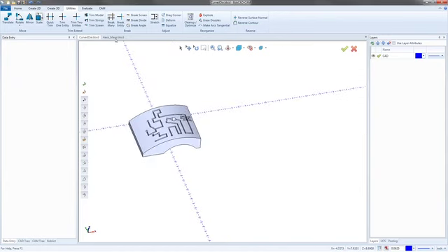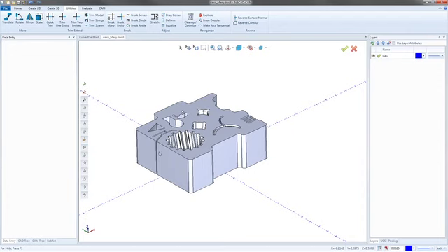All right, so I'm going to do the 4-axis mini. Now, when I do these kind of parts, you pretty much have 2 different ways of going about it. You can pick your geometry right off the solid model, or you can take the geometry off, make it 2D, and then do it that way as well. So I like to break it down, but it's whichever one you want to do. Primarily, if we're doing a 4-axis, I like to do it with a breakdown. I like to break it into separate 2D geometry, just because it makes my life a whole lot easier.